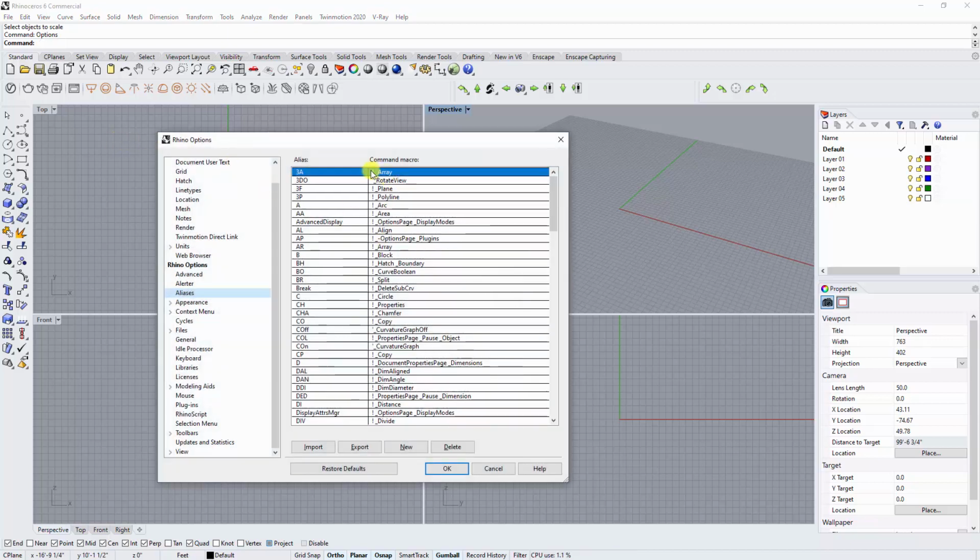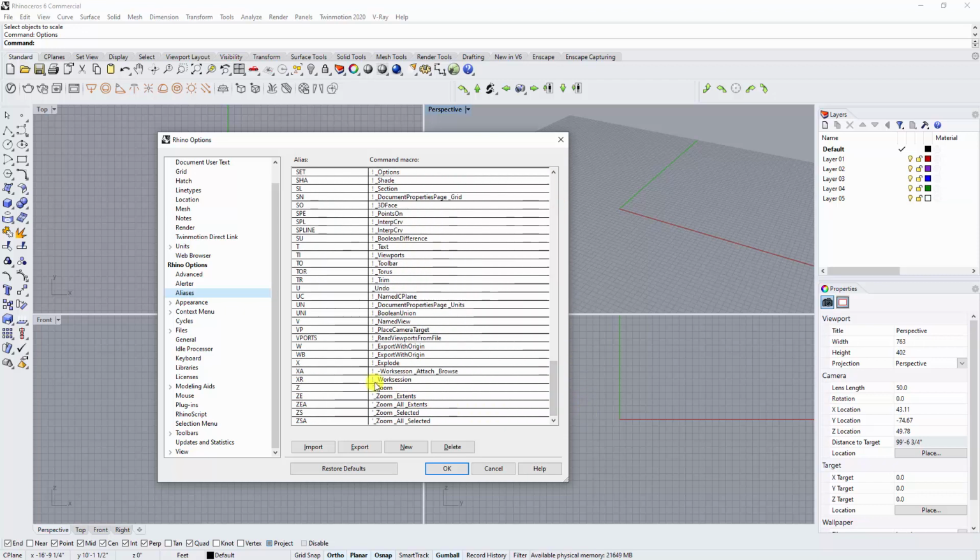So you may see some of these command macros over here and wonder what some of the stuff is in before it. So just as a quick way to decipher here, exclamation is essentially like the escape. Right? It's going to cancel your current command. And that is in stark contrast to the apostrophe that you see here, or a really great example of that is the zoom, right?